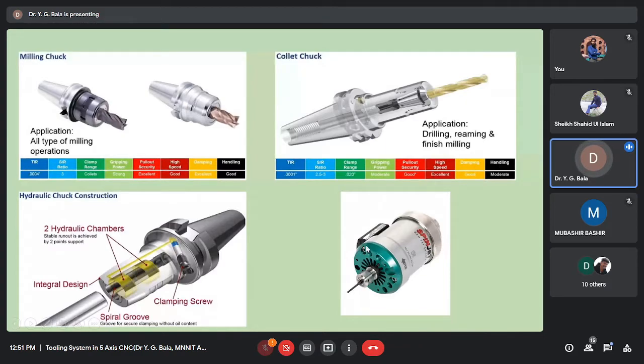And this is another spindle type where coolant is circulated. During the machining process, there will be slots and an inbuilt coolant supply, so along with the coolant supply, you can run the tool process. The coolant not only reduces the interface temperature, but the chips are also pressurized out from that surface during machining. So all this is for increasing the productivity and the surface finish of the components.